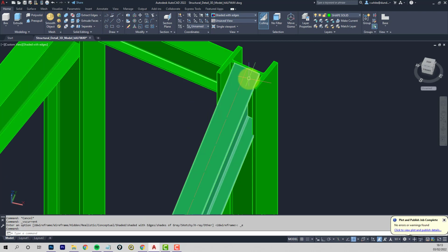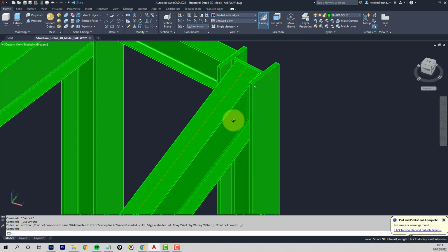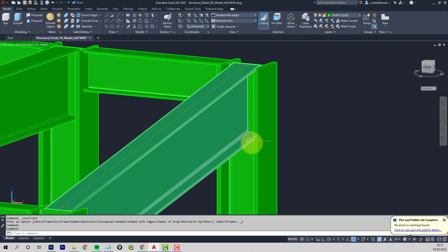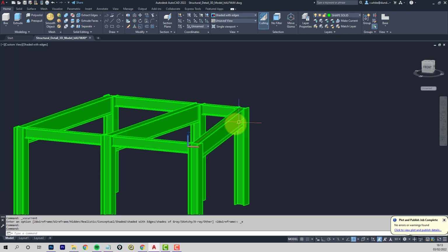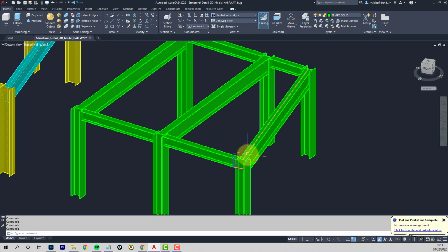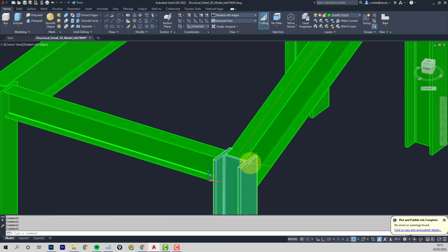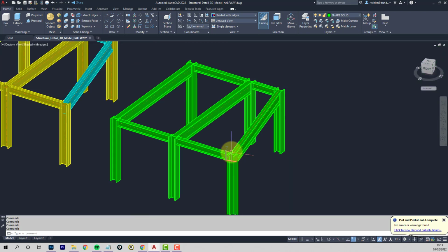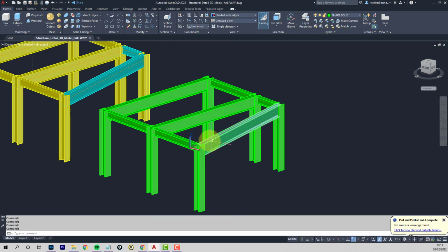It's so close to the column that its integrity is fine. So losing a little bit there wouldn't be a big deal. And that's what the steel fabricators do. They kind of look for these issues and tidy things up. So when it comes to site, there's no cutting that notch on site. It's already being considered.